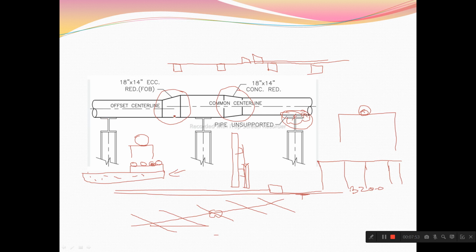When you are getting a size change and you have steel continuously, say steel 1, 2, 3, then only you have to use an eccentric reducer to maintain the elevation of the steel.